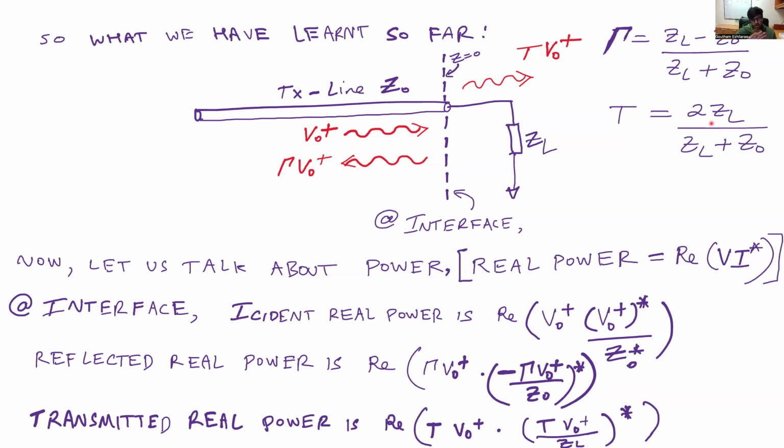Till now, we have completely just talked about voltages, but to get an understanding in terms of energy or in terms of power, we can now start talking about the concept of insertion loss and return loss. So now if we talk about power, in this case we mainly care about the real power, because the real power is the actual power that's going to do work, and that's the power we want to successfully transmit to the receiver from the transmitter.